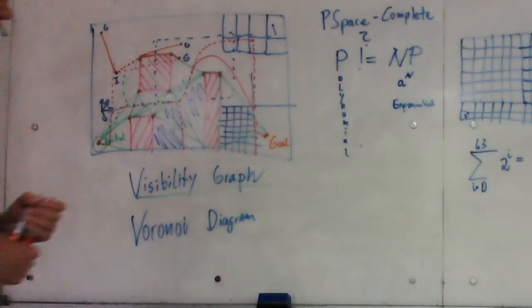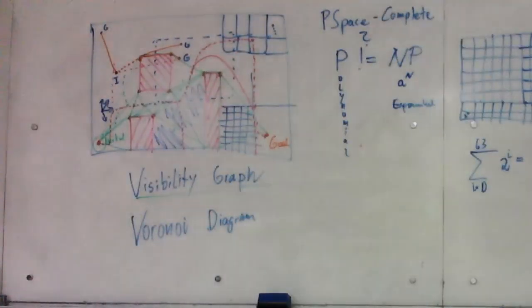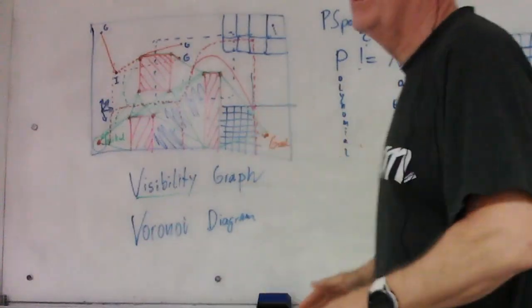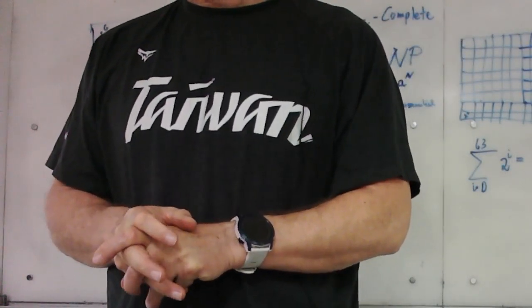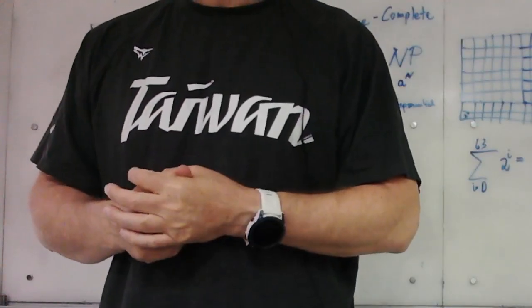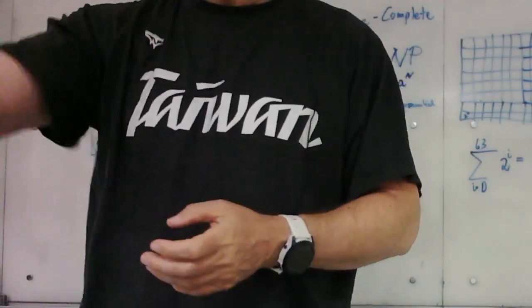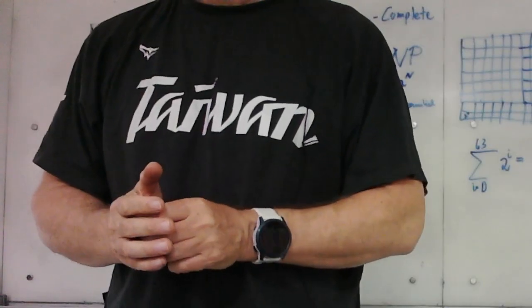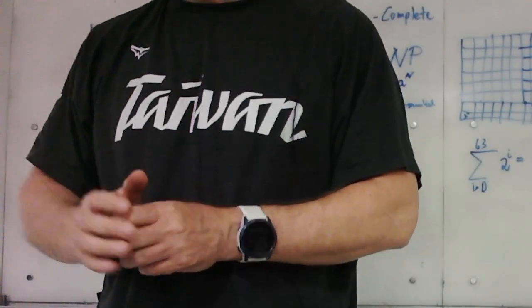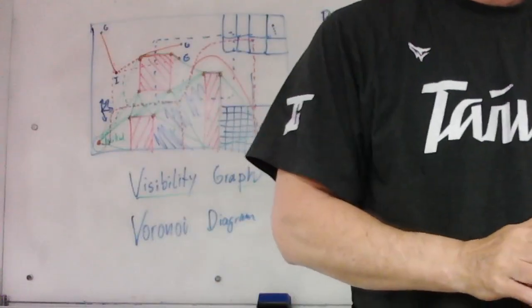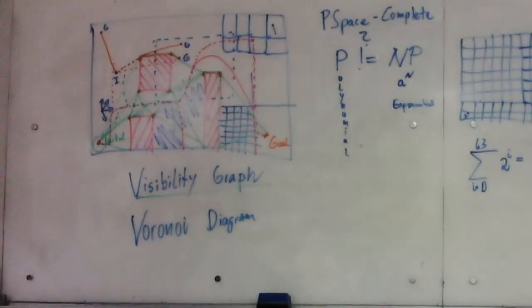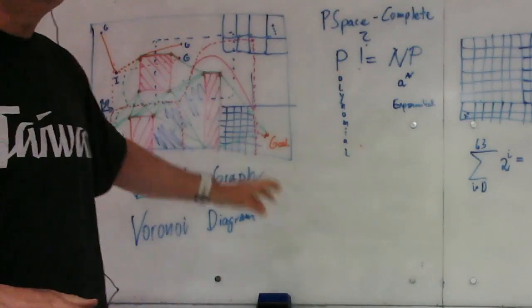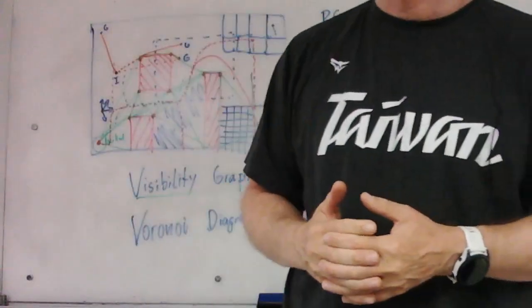And that shows the first two approaches, and then people realize, okay, well, the Voronoi is also not all that good because it is too scared of the obstacle. Visibility graph doesn't care about obstacles at all, no fear. Just boom, right down the 1 millimeter border. And Voronoi diagram is like, oh no, I gotta stay away from the obstacle. Both of those attitudes are wrong for your robot. Trying to find the right balance for your system is non-trivial.